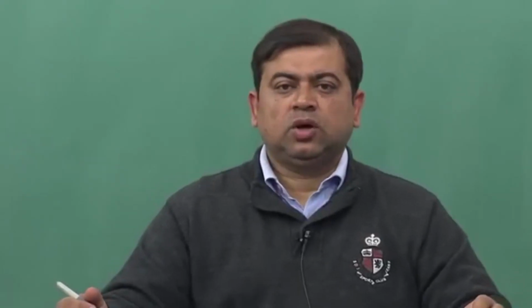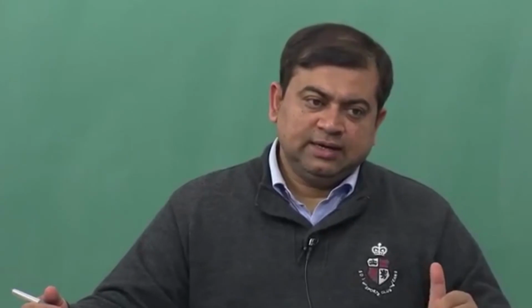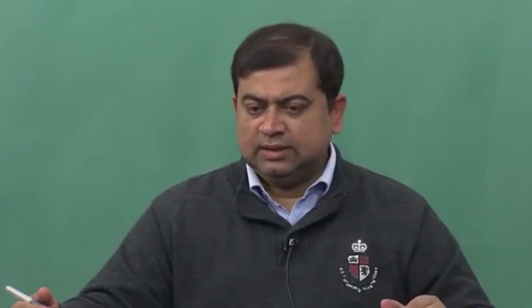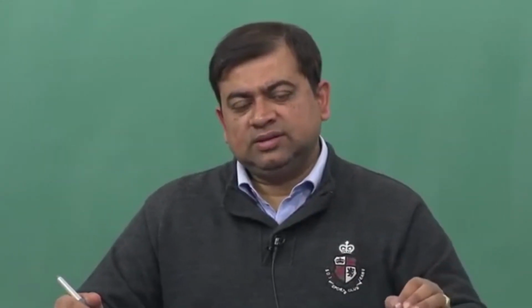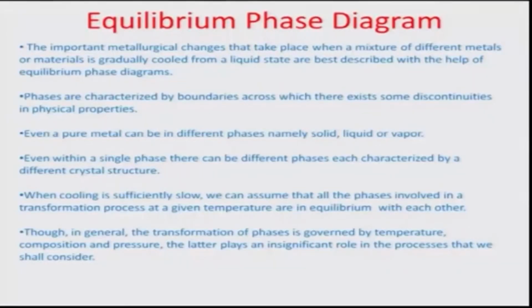We were talking about solid solutions and we just started deciphering how there is a solvent phase and a solute phase, and how the solute, based on its size, can go either into the interstitial spaces or you can have substitutional mechanisms in the solid solution. Let us now talk about equilibrium phase diagrams, which is a very important aspect of understanding these solutions.